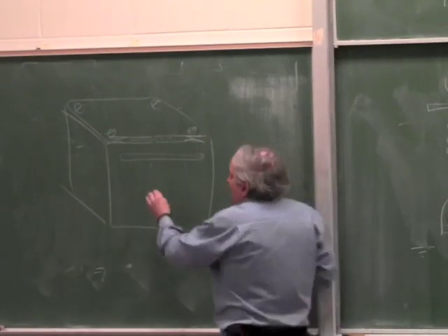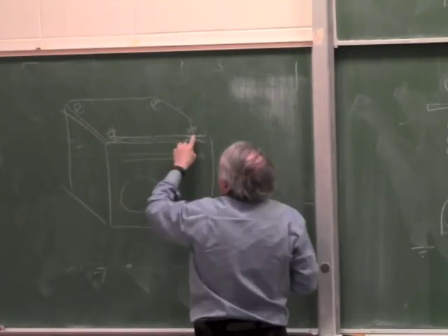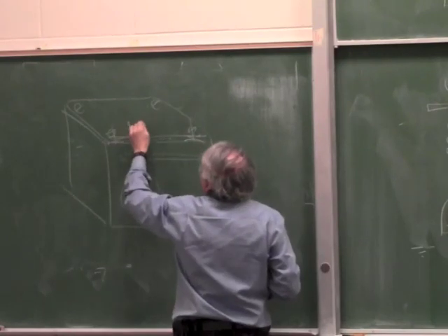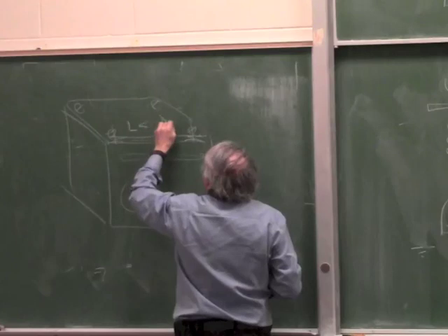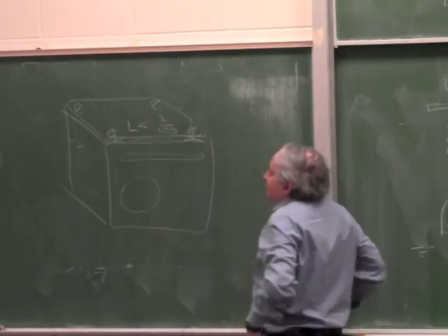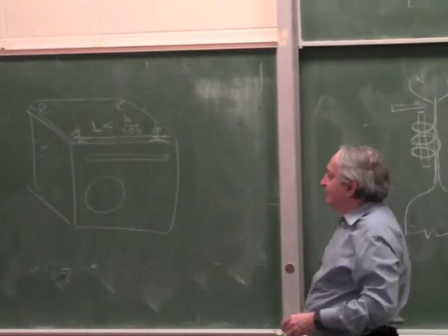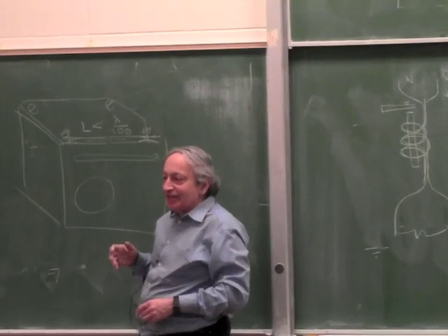So basically any kind of holes or slots or distance between screws, which is same as grounding points, this dimension L has to be smaller than lambda over 100, otherwise it doesn't work. Because anything which is not continuous ground can act as an antenna.